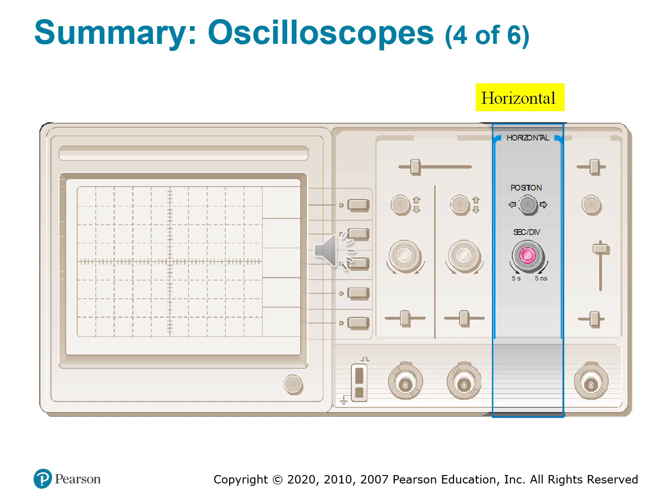So from here on out, you've got the volts per division for vertical, which is the amplitude, and seconds per division, which is horizontal for time. These are the two axes of every signal that you analyze. So you have to master both so that you can bring signals to life on the screen.